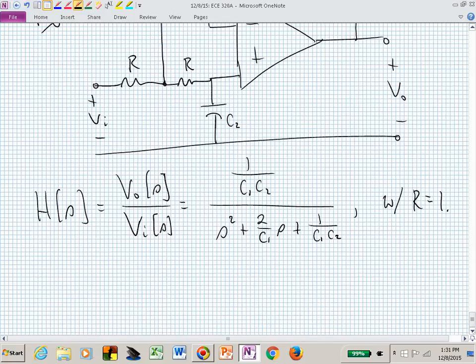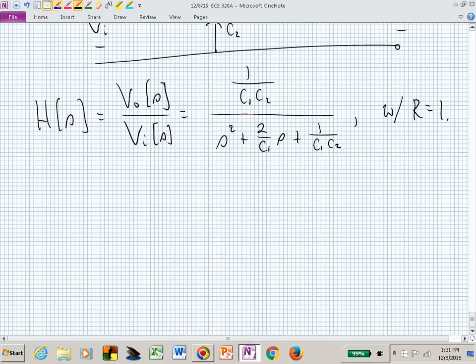If you now had to say what that transfer function was giving you, you've already told me it's second order. Is it low pass, band reject, or high pass? Knowing what you know about Bode plots and just a generic back-of-the-envelope sketch, do you have any finite zeros?